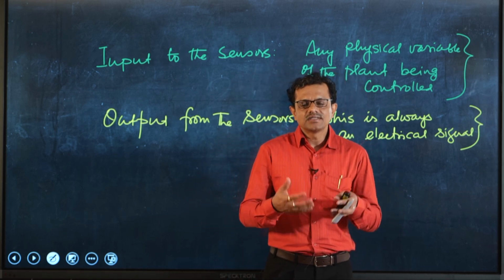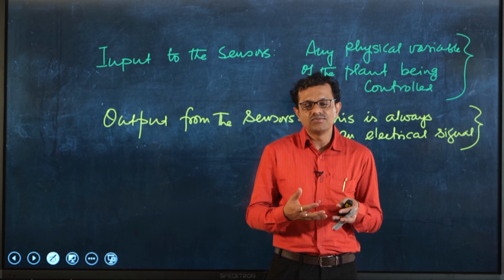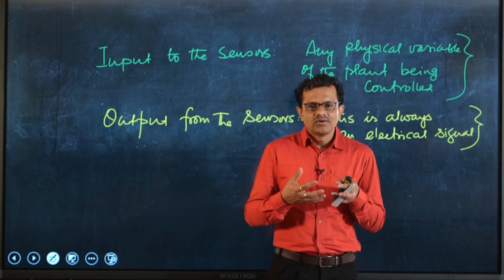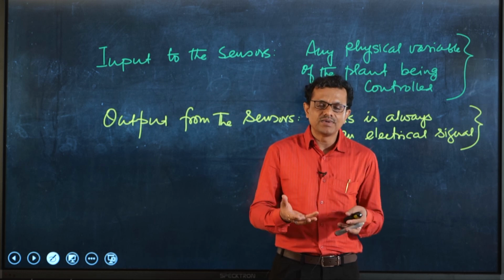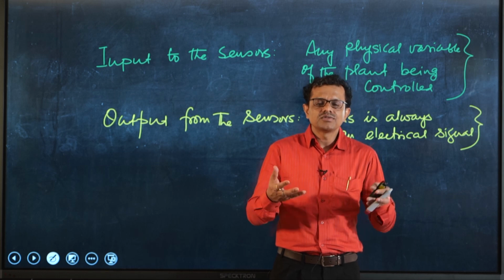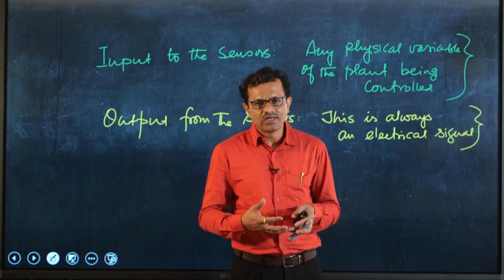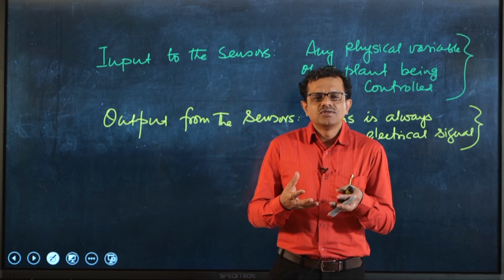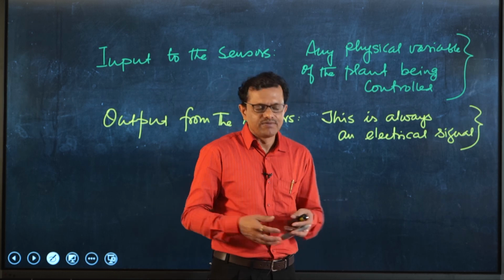So, whenever the sensor responds to that change in pressure, certainly we have to take into account the change in pressure due to change in temperature. So, in real application sensors respond in some way to that physical quantity. Certainly, through proper signal processing we can eliminate that defect.